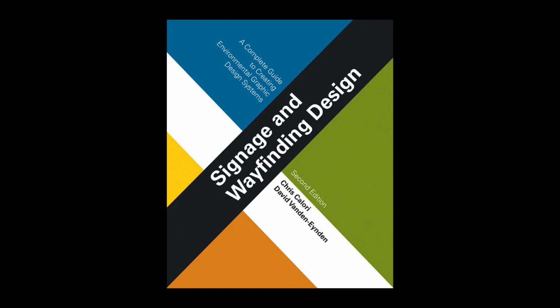Because it's tedious and time-consuming to completely revamp the sign numbering system once sign numbers have been entered on location plans and the message schedule. See figures 2.19 and 2.20. The sign location plans indicate on plan drawings each sign in a program, along with its identifying sign or location number. This sign number is entered into the sign message schedule, which contains all the essential information about each sign